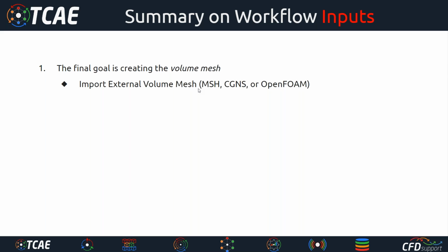Or you will use the T-Mesh, which is the meshing tool, a semi-automated tool, which creates the mesh for you. It can be extremely complex, but it still works, because T-Mesh is based on SnappyHexMesh, which can mesh almost anything for CFD simulation. So that's the option most of our users use.